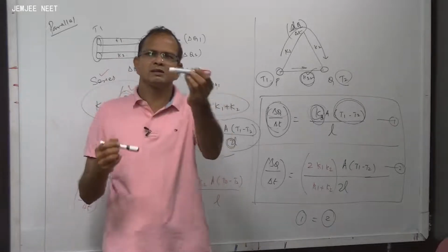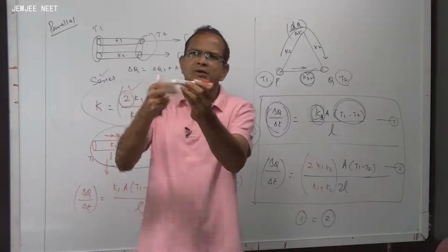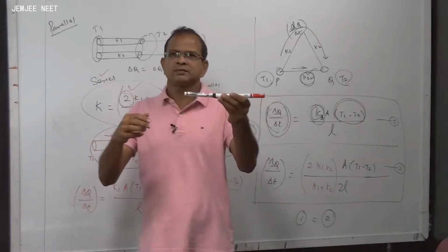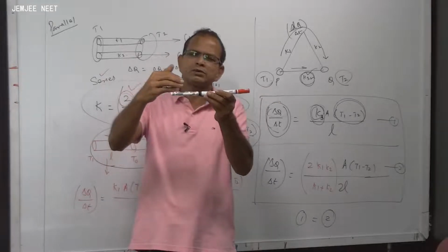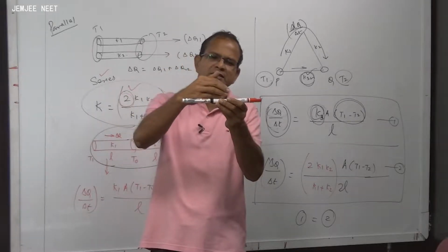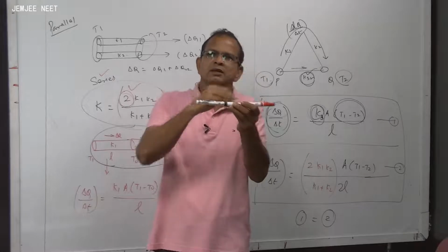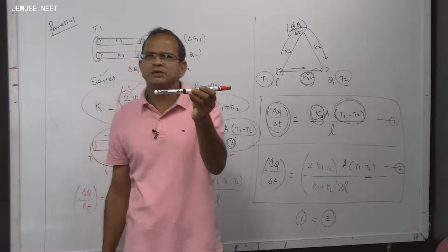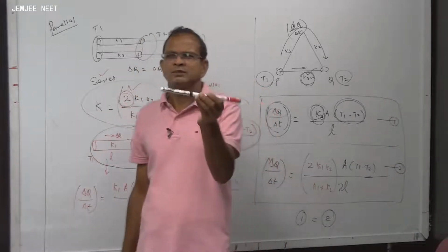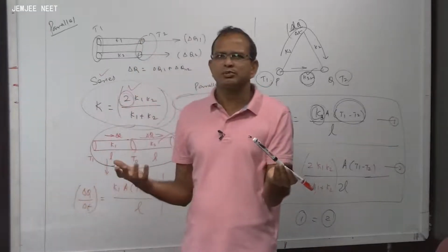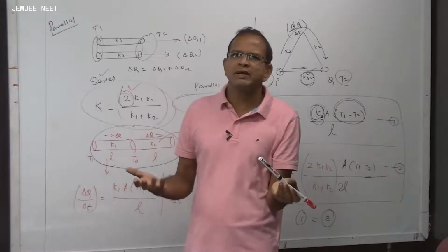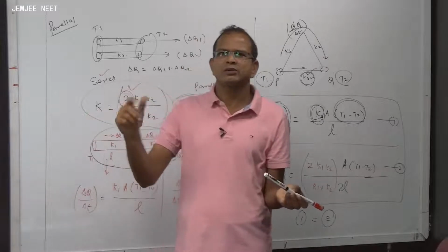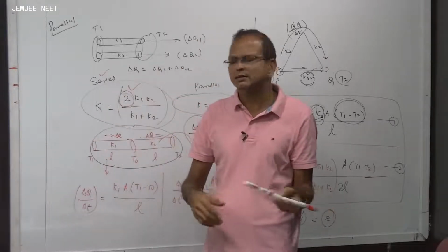Now you look at this rod alone, it provides conductivity of Q. Now you attach one more rod like this. You have made a longer rod. If you give heat here, the heat has to find a lot of trouble on the way, resistance, and reach this place. Now the quantity of heat flow per second will be more than the first one or less? Less than the first one. So therefore it should be something like K1 K2 divided by K1 plus K2, where if 3 and 6 are the case, K1 K2 divided by K1 plus K2 will be less than that. Yes, that's what is happening.